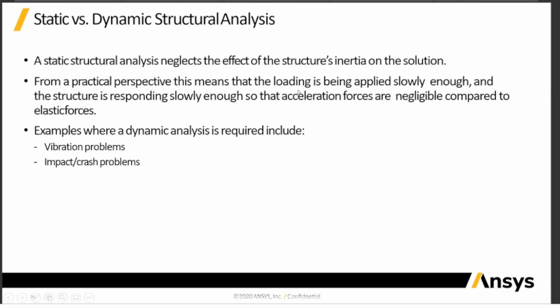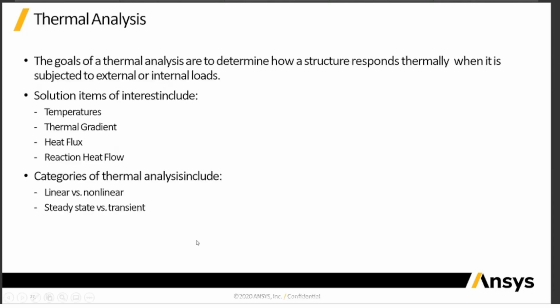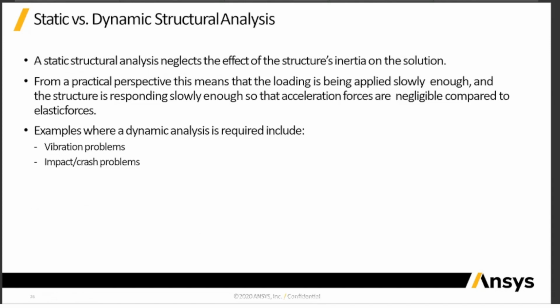From a practical perspective, this means that the loading is being applied slowly enough, and the structure is responding slowly enough, that the acceleration forces are negligible compared to the elastic forces.